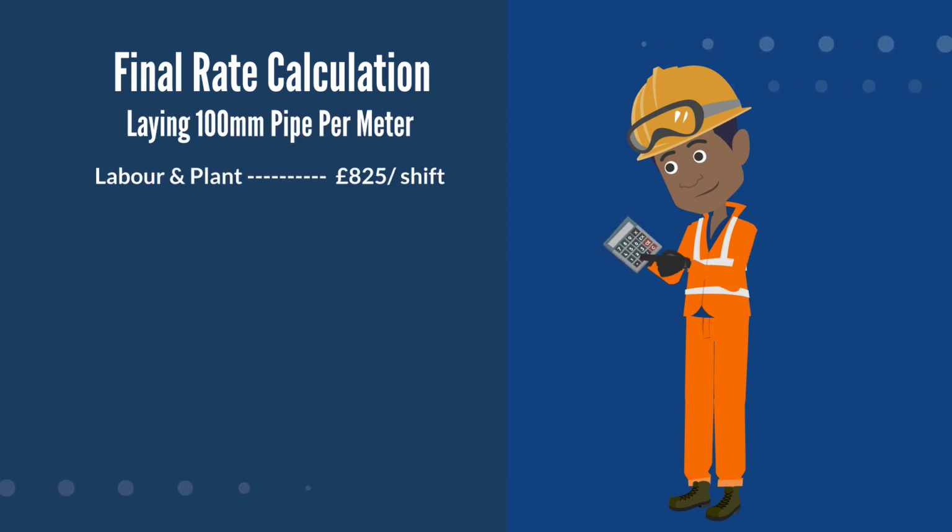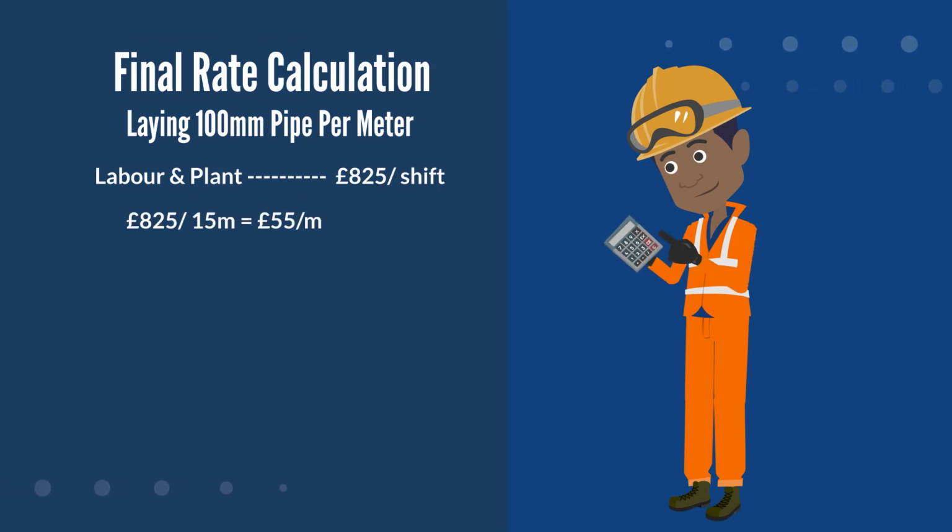Firstly, let's take our total labour and plant at £825 per shift. We now need to turn this into a metre rate using our productivity measure. Earlier, we determined that we could achieve 15 metres per shift. This would bring our direct labour and plant cost to £55 per metre.